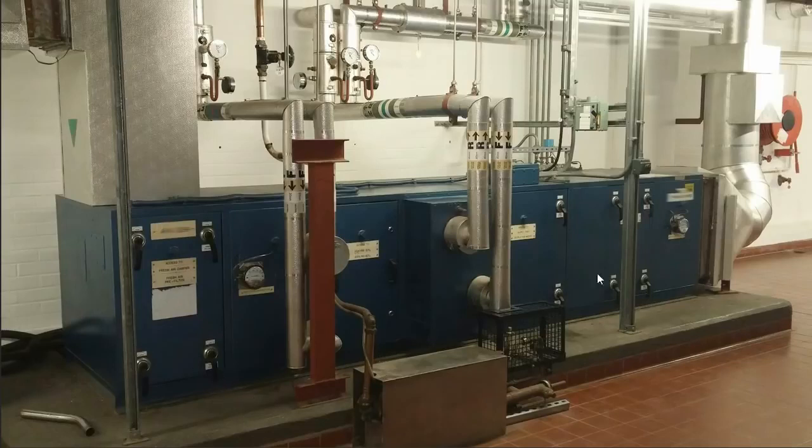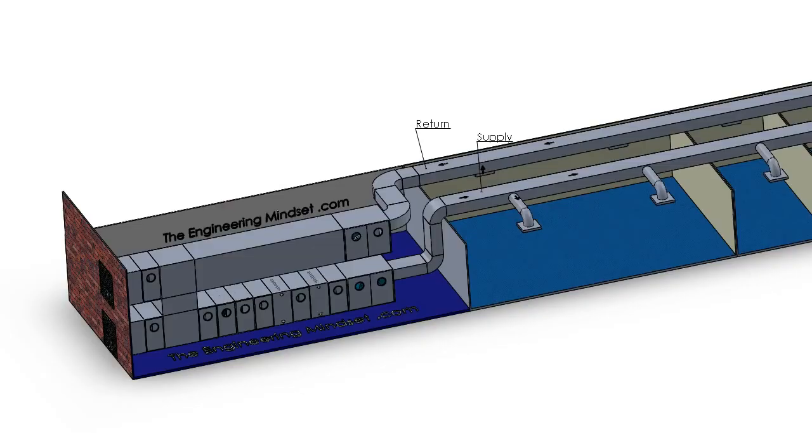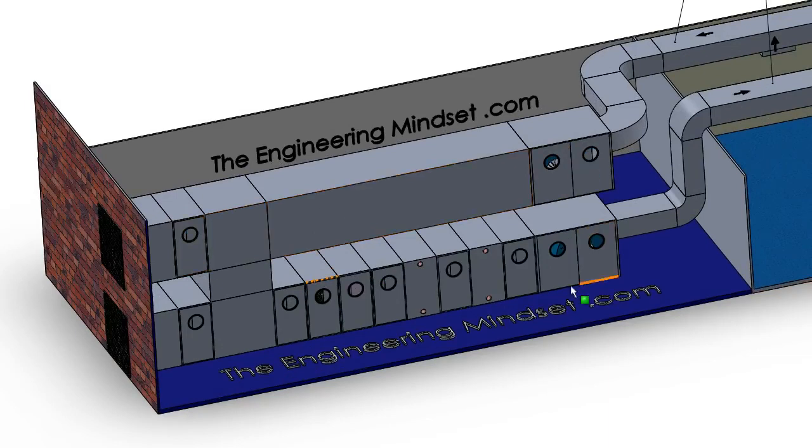It's obviously important to switch off any fan that's inside here first, cut the power, because it's very dangerous, and you might get sucked in and potentially lose an arm or a finger or something, so please make sure you do that. And you can use a panel key like this just to gain access and open up and have a look inside the AHU. And while we're on that point, I'm just going to take the side panels off of this AHU, just so you can look inside.